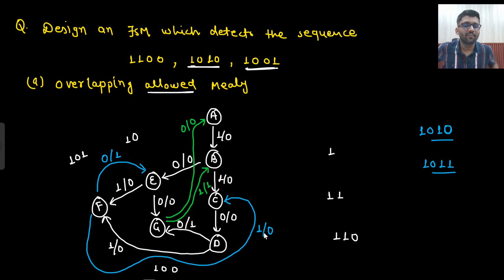So here, how many ones can you see? If this state diagram was given in front of you, let's remove everything else off, but they will be used later on. So let's keep it. Forgetting about the rest, if this state diagram was given in front of you, would you be able to understand how many sequences are detected here? You will see the number of ones: 1 time, 2 times, and 3 times. So certainly 3 sequences have been detected.